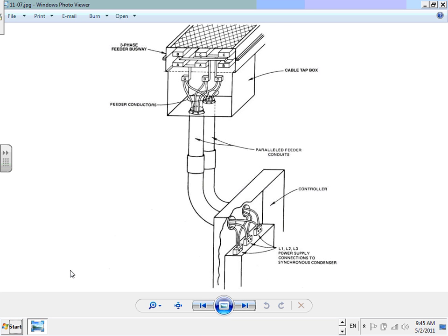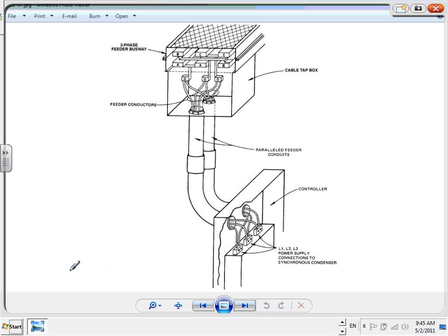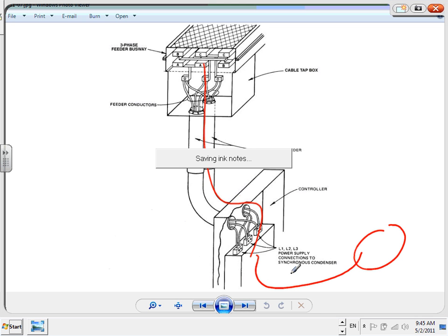Yeah, I'm recording. You guys are looking at a condenser. This is a picture from the project that we have. The condensers are sitting right in here, tied to the control system, and from here into the busway system feeder. If you remember when we looked at the busway feeder going all around the manufacturing floor, this is just a way of connecting the condensing unit to the busway to correct the power factor for this manufacturing floor. Nothing really gimmicky to it. There was some control and disconnect and so forth.